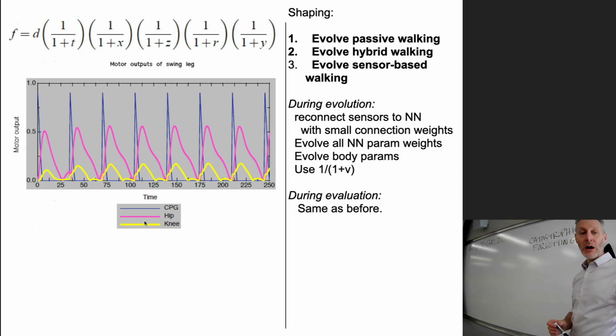What about the hip? We're talking about the hip in pink. What about the knee in yellow? What's going on at the knee in this robot? Passive dynamics, hybrid, active? Hybrid, for a similar reason, it's just spending more time without leg tension. Absolutely. There's more passivity. There's longer periods in which it's at zero or very, very close to zero. These very shallow bumps here are a little bit of torque. It's basically the motor just kind of cleaning up or correcting what the knee is doing.